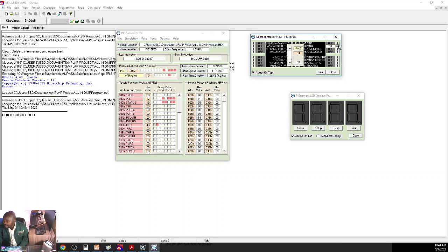To get 125, this value must be close to 256, but not exceed 256. Because I said if it exceeds 256, that will be an invalid reading for my application. I won't even consider it. But if we have, let's say, 210 divided by 2, that will be 105. There will be 1 in hundreds, 0 in tens, 5 in units, indicating 105 degrees Celsius. Right.